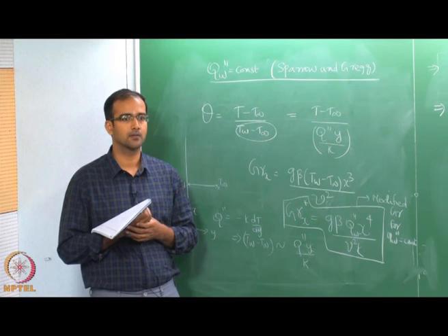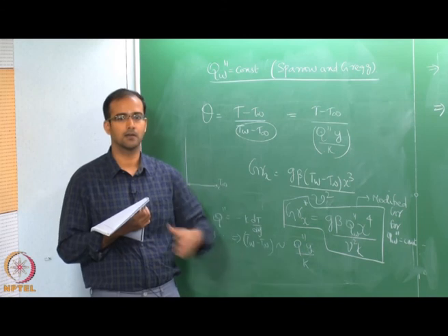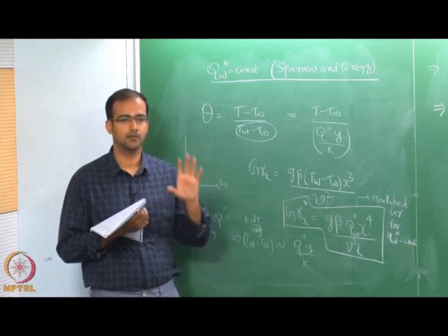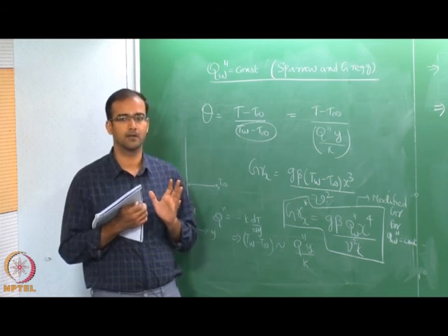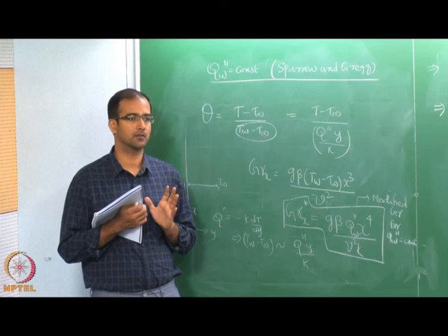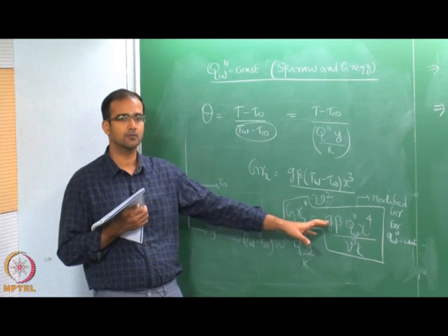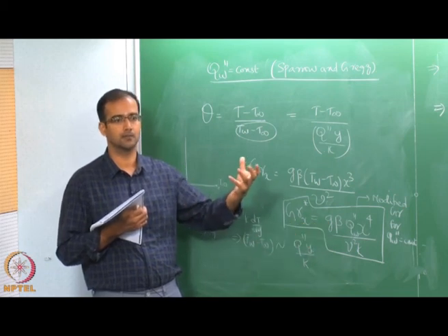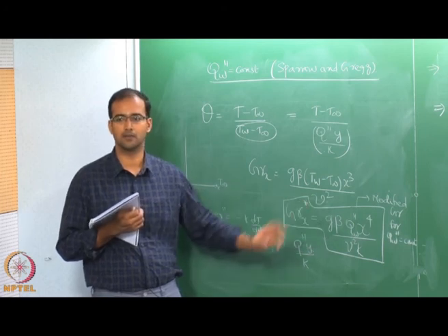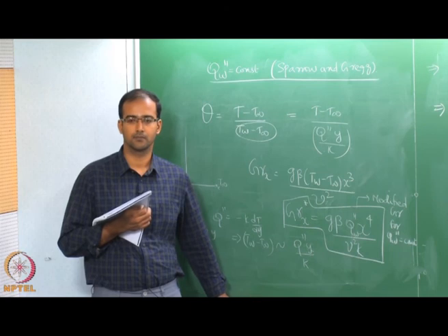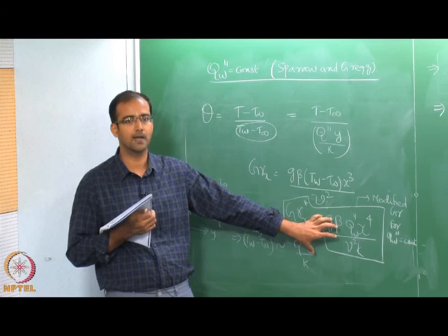So, this might not be an exact transformation of your conventional Grashof number, but you get a non-dimensional group. That is all you have to be worried about; we should not think about complicating it further. All you need to do is, once you know your heat flux, put it into this, and now you have a local Grashof number varying as a function of x.